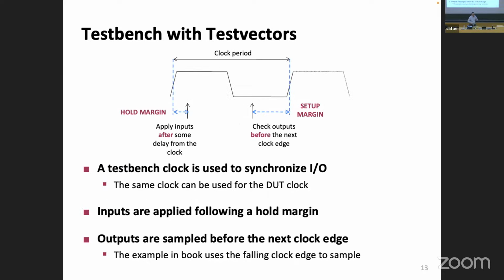So when you are looking at it now, we have this test bench, and the test bench will apply inputs every cycle, every step of the way. We'll be applying the inputs, and then we will check the outputs, and we will continue to do so until all our vectors are exhausted.